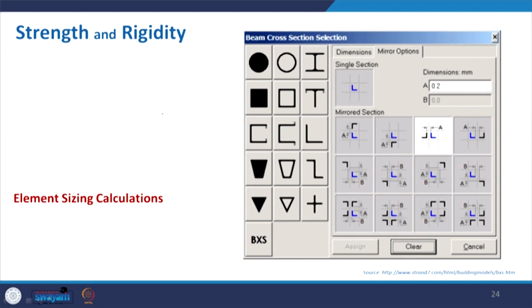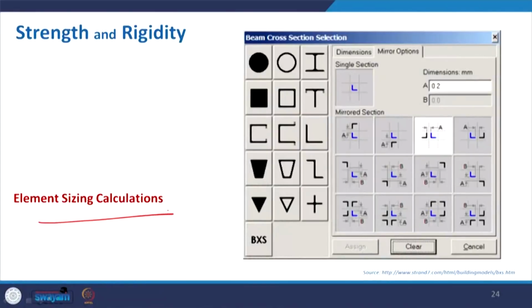And then basically the selection, as we mentioned, of the cross section that will give you the adequate moment of inertia, the stress or strain that it can hold, along with the material, whether it is steel or stainless steel or some type of steel or some composite material that we will pick up, and then we will determine the rigidity of that. So, along with these three steps, the assessment of load, the calculation regarding the structural analysis and its performance, and selecting the element size, we will figure out the strength and rigidity part of the structural requirement.